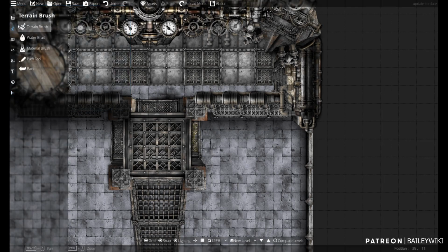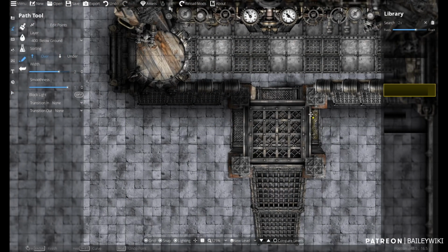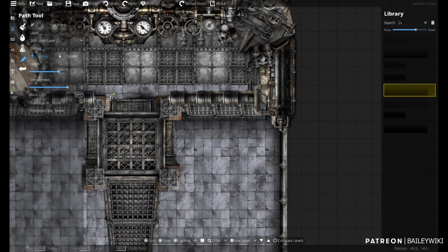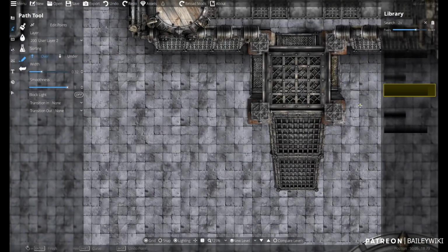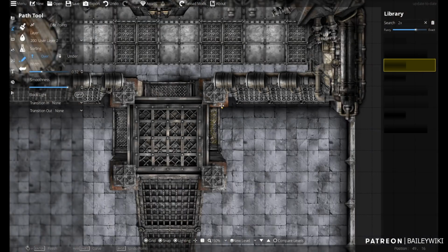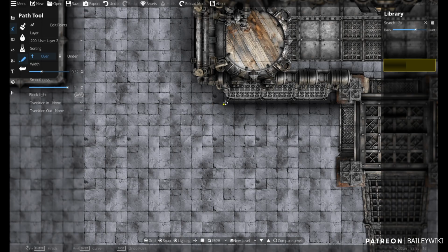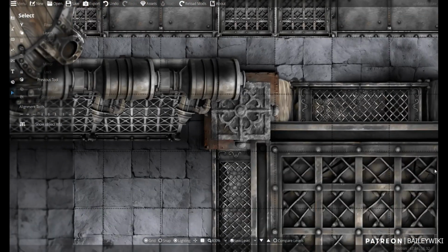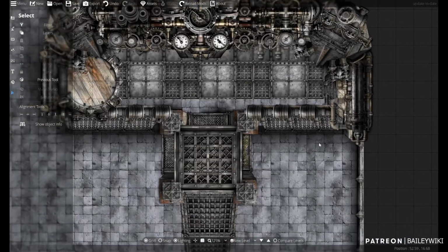Now I really want to make sure that the top part and those walls kind of meld into the floor. And so what I'm doing is I'm looking at laying another path down. And we'll do a double path this time, so it's shaded on both sides. And all we're doing is just helping that wall merge. You see that very bright transition from the wall to the occluded shadow under it. We want to help that transition by putting a little shadow over both, and that'll help merge them together.